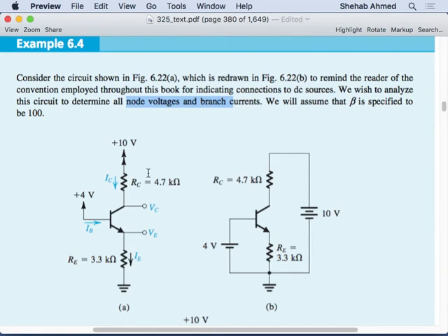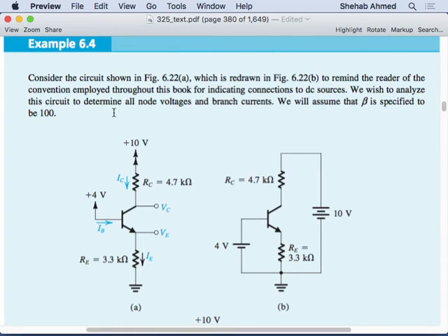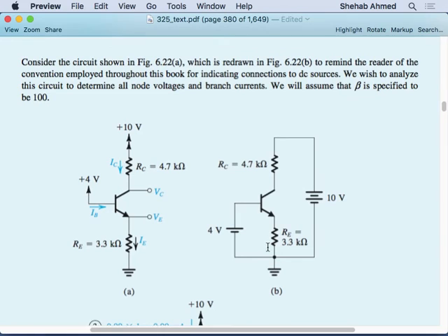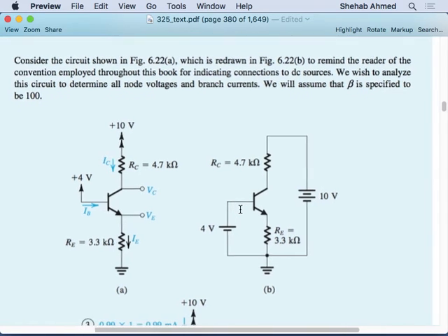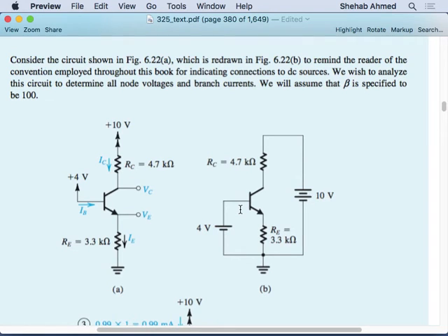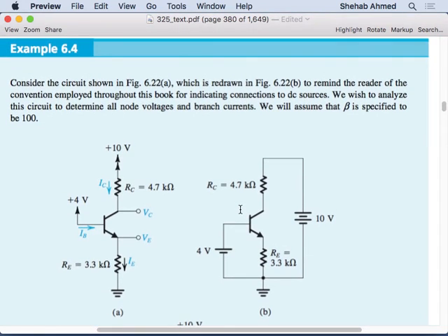We're either going to be missing the resistor values, or you're given the resistor values and the supply voltages, and the question is whether this device is in active or saturation, etc. So this is equivalent, of course, to this. These two circuits are exactly equivalent. They just redraw it, and then they give you beta here assumed to be 100. So they gave you the resistor values, the beta, and the supply voltages, right? So how do you go about solving this circuit?